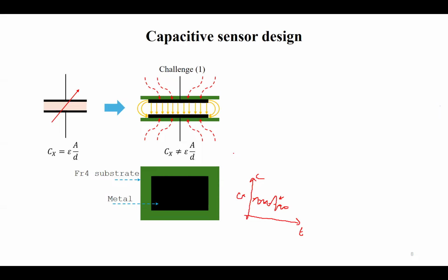So why is this effect very crucial? The answer is that the capacitance value of sensors will be in picofarad, okay, several hundreds of picofarad. And this variation will create a change of near 10 to 20 picofarad, right? Which means there will be a 10 to 20 percent variation. So it directly affects the repeatability of the sensor, or even the sensitivity may be affected by these interferences. So this is a very bad design, I would say. It will be a very bad design for a parallel plate capacitive sensor.